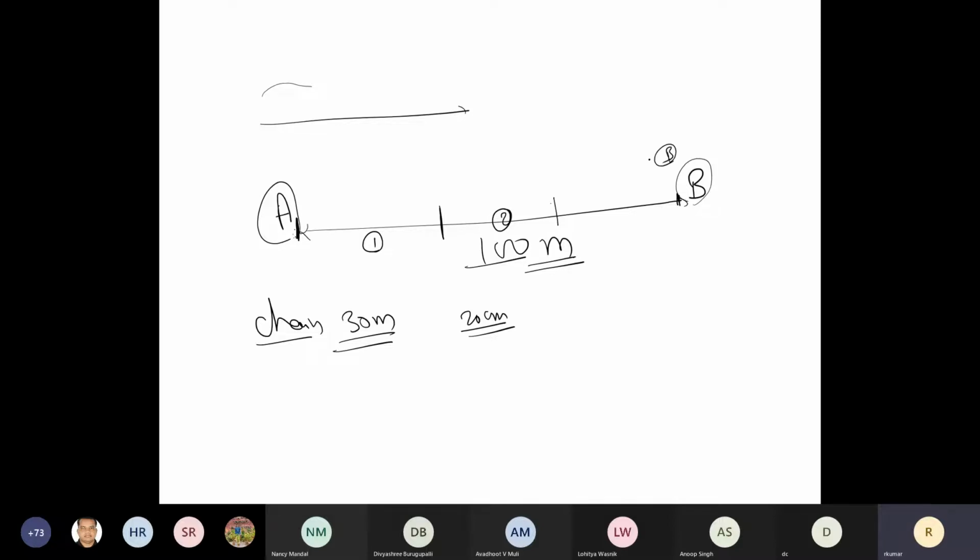So how do we keep this in one line? That's why we put some ranging rods here and here. A and B direct each other to move a little left or a little right, either side, and you will get one position. Again, here will be a ranging rod, and here another. All four ranging rods should be in one line, so I can still locate where my B is. It should be in one line. Are you getting it?